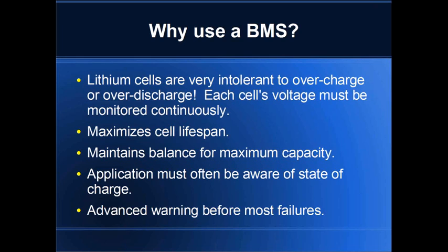Likewise, over discharge is also very important for lithium cells. You can actually kill an entire lithium battery pack in one single over discharge. And if you overcharge a cell even a little bit, it can lead to lithium plating, which can pose a safety issue later on, and it also shaves life off of the cells.